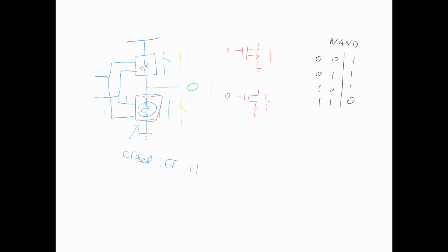So the situation we're in is that we want this combined gate to be closed if both inputs are 1. I have a digital switch which I can close if an input is 1. So essentially I have got two switches and I want to arrange them in such a way that the overall switch is closed if and only if both of my individual switches are closed. There are really only two things I can do with digital switches. Either I can put them in series or I can put them in parallel, which is a bit harder to draw. There we go.